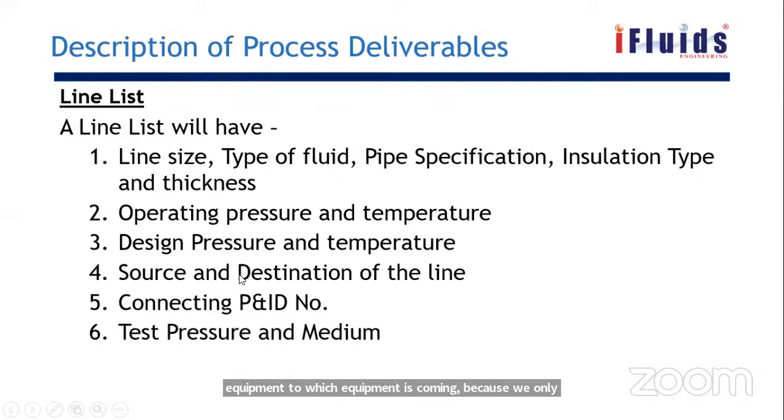So they need to go through that particular P&ID and check, or the construction contractor may not know the process. They just see the source and destination, and inside also they will follow that accordingly. And then the connecting P&ID numbers will be shown in the line list. And then the test and pressure medium.